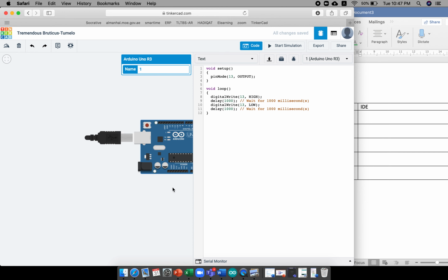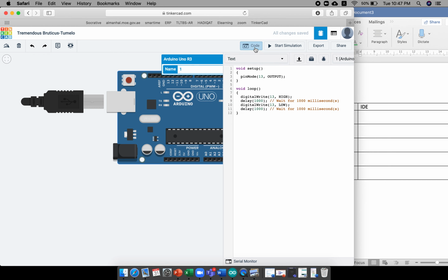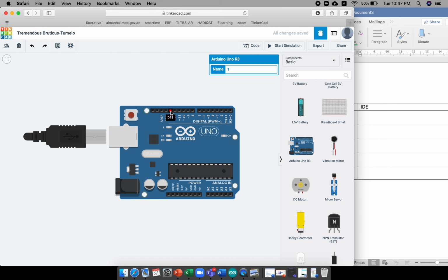Let's first overview what we need from this example. We said that pin number 13 can be an input or an output, and we said that this little LED is connected to pin number 13. Assume now that we want this LED to blink. Blink means keep turning on and off all the time. How can we write that in the Arduino language, in the IDE?